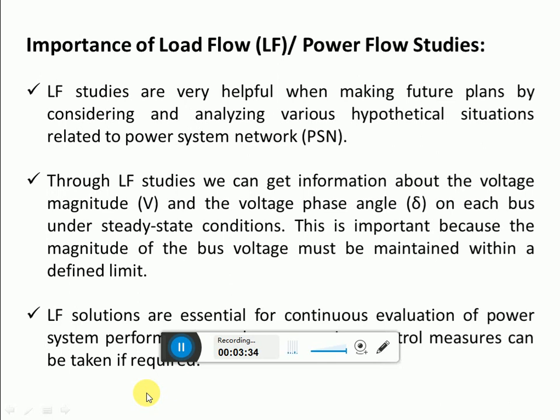that we can get with the help of load flow analysis. How? We will remove a line from the system, and with the existing loading condition, we will run a load flow method to get the information of the power system network, and from the output we can see whether there is any voltage violation or any line flow limit violation or not.